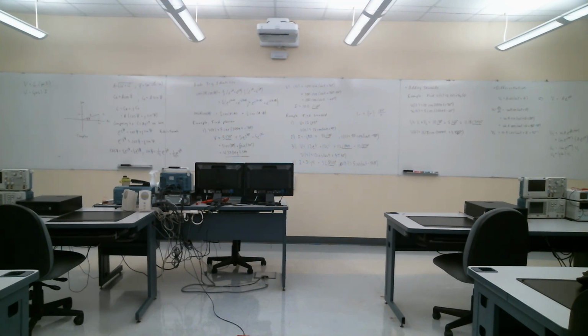It looks like V is equal to Ri. So we make that identification. We call this thing, this j omega L, an impedance. So that in the phasor domain, we get this expression that looks like Ohm's law.